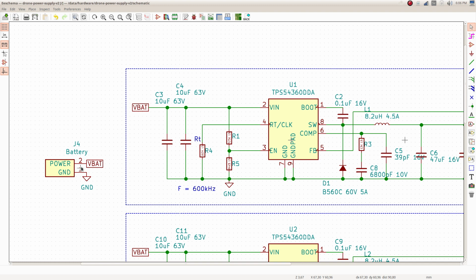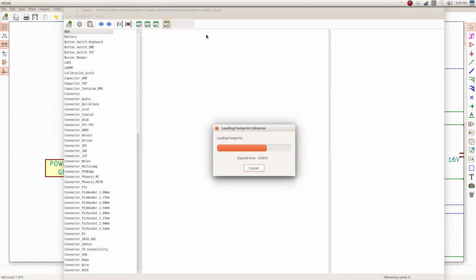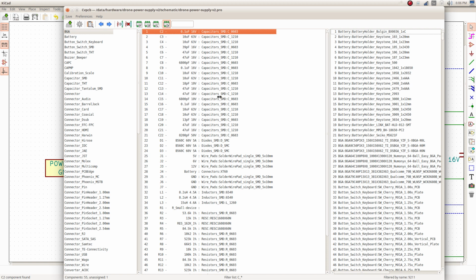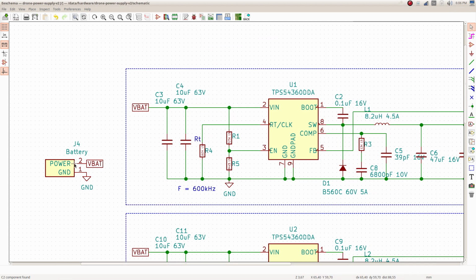If I then go through the standard way of just annotating the schematic and assigning footprints, it could actually mean that if I have used a component that has pins reversed, and I then assign a footprint that places the positive pole of the battery onto the negative side of the connector, then obviously things wouldn't work, and I would have to redesign the PCB.